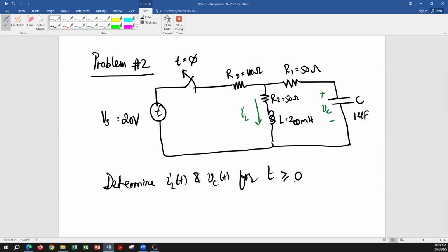So once again, once you draw the circuit, if this circuit is given to you, make sure you observe it and decide that after the change, the circuit is a parallel RLC circuit or a series RLC circuit, because based on that you're going to calculate your omega naught, alpha, damping type, and all those things. Of course, you can see the change. It's pretty clear that the switch is going to open at t equals 0.